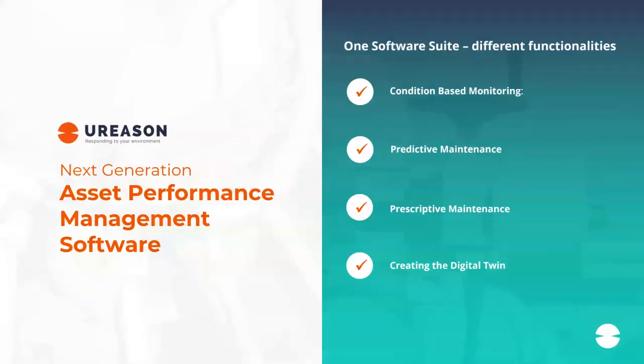I have a question here from Jürgen. How are the alarms coupled to failure modes? If you think of an asset, like a cooler or a pump, you have an FMEA or an FMECA. In the FMECA, you have failure modes, causes and consequences. And then in an FMECA, you have an RPN, a risk priority number that provides an indication of how likely it is that a certain failure will occur. The linkage of an alarm to a failure mode can be done on the basis of the failure modes that you've identified in an FMEA.